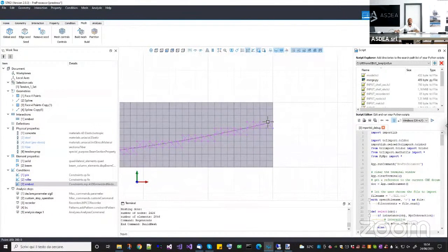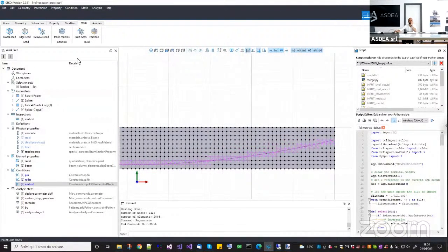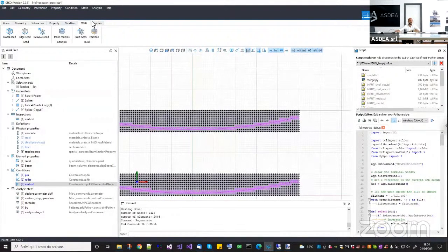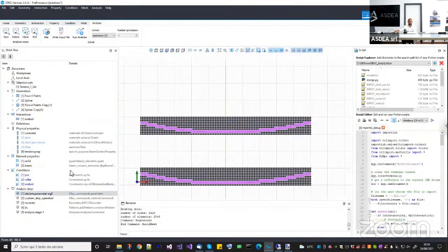It is very convenient because you don't have to go into each and every part and cut the geometry, so you can have a clean mesh, but you can still embed some geometries that do not follow that mesh. Okay, so this is the mesh. Let's go back to the analysis settings. So what I want to do here is to show also how to use pre-stress.